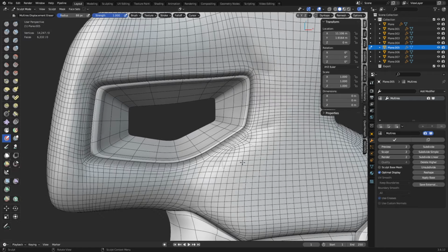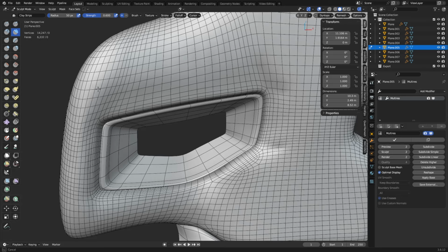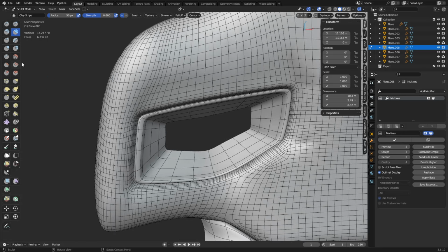All right, we managed to get something going here. You'll notice that now that we have this kind of topo here, it doesn't sculpt as good, right? That's why you want to try to avoid E-poles and N-poles, because usually these things don't smooth out quite as well. You'll see little artifacts sometimes. They don't deform very well if you're trying to deform things. But we can do this all day long, basically. We can go back through, we can smooth it, we can use scrapers.